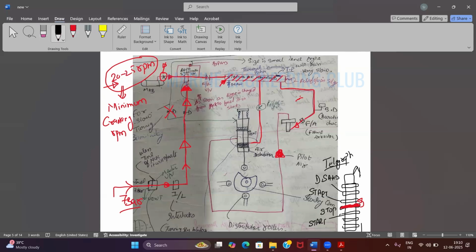Right now, in this position, I have two pistons here, upper and bottom. The bottom piston is blocking the channel of my pilot air. Agreed? Yes, sir. It is blocking the channel of the pilot air. Pilot air cannot enter my distributor. So until this air goes and pushes my piston down, this air cannot move further. Once the air pressure comes, it will push my piston down and the upper piston will close this vent. When it comes down to close the vent, my 30 bar air can now go.